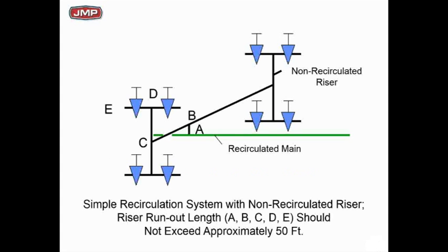So let's go to a little example and see what we've got. This is that very last riser out there, and I want to make sure you don't lose track of what we're doing here. If you look at point A, the recirc part is the green part of the pipe. That's where we're going to recirc water through. We're going to keep that hot. We're going to make sure that's within 10 degrees of the design supply hot water temperature as a minimum.